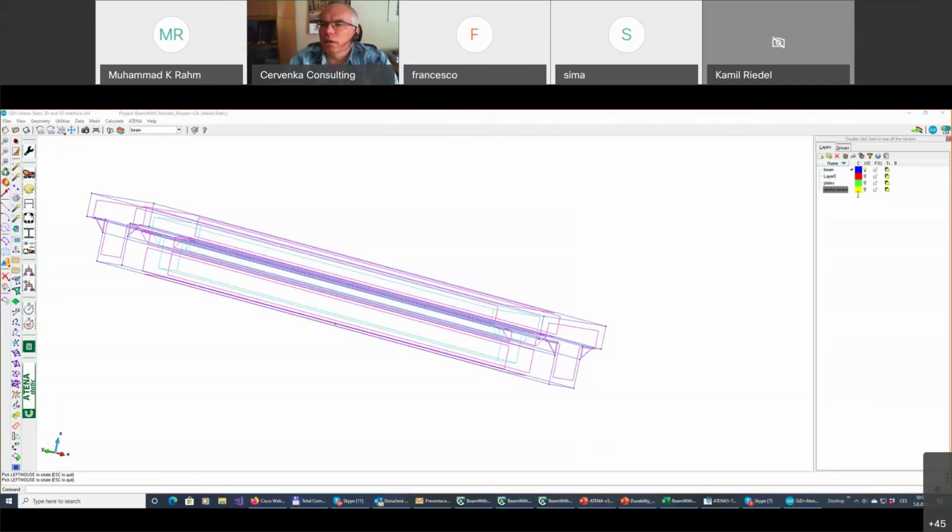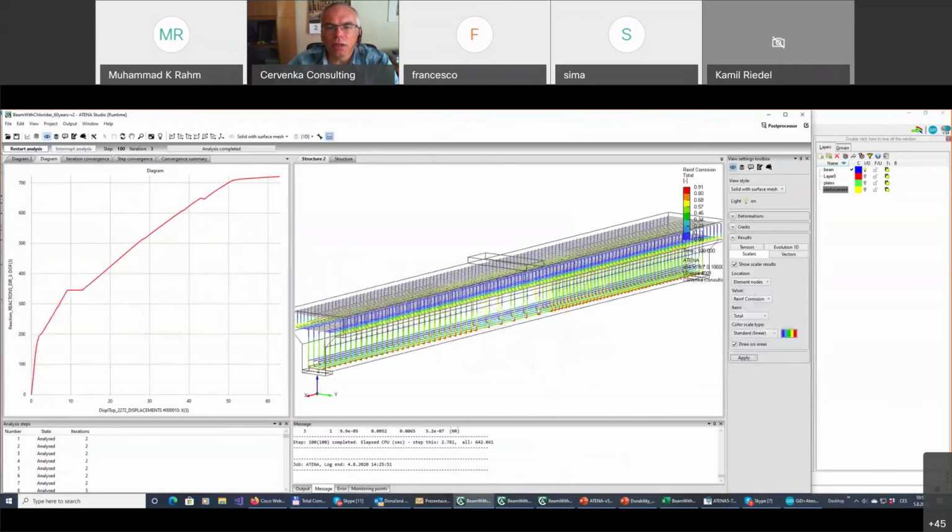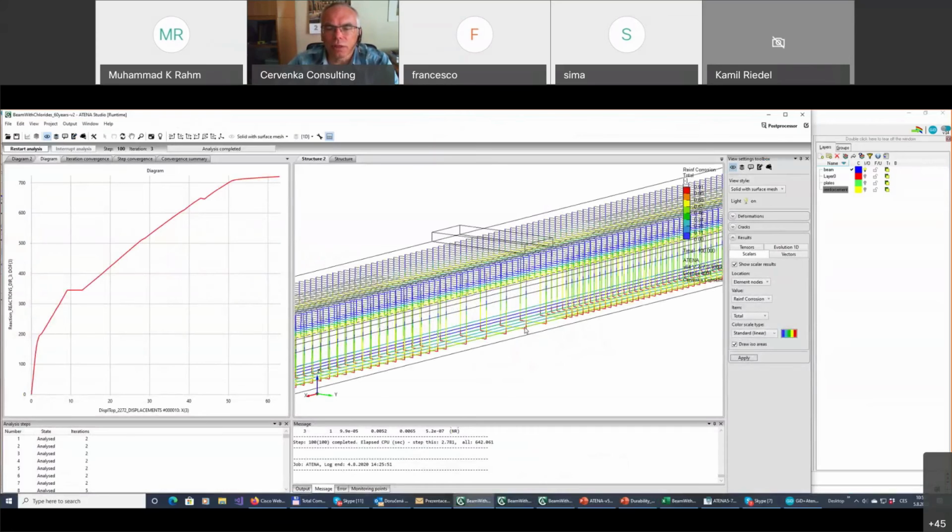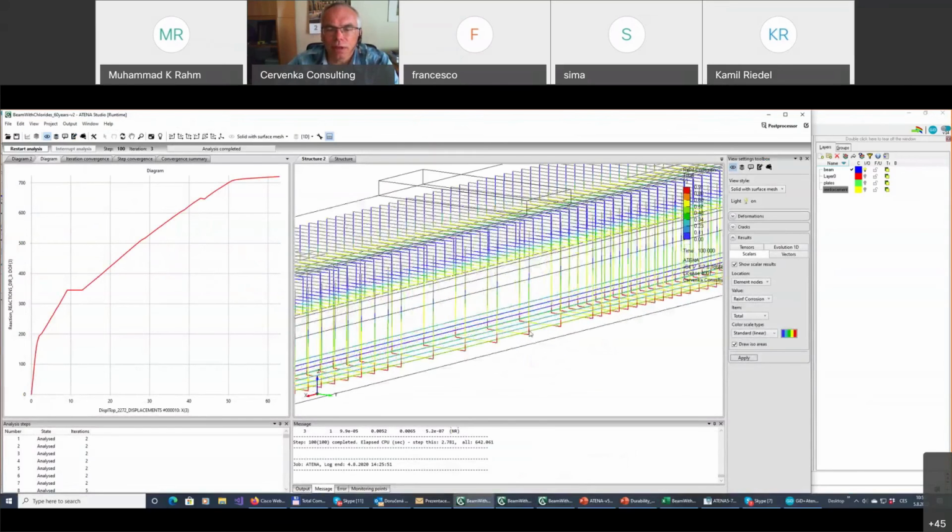Seat is asking about reinforcement. Do you keep the real distance, i.e. for stirrups or ties around the long bar? Do you use half of each? I'm not sure I understand it, but you can see clearly from our results that we indeed consider the distance of each reinforcement. Even in these stirrups, we consider the fact that the chlorides propagate from two sides. So you can see these stirrups at these bends are more corroded than the longitudinal reinforcement.